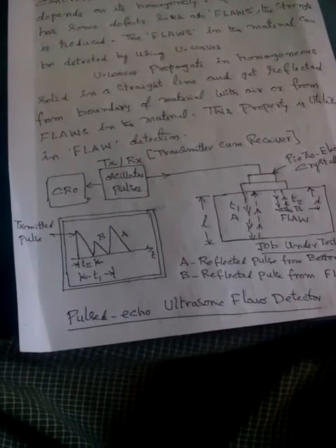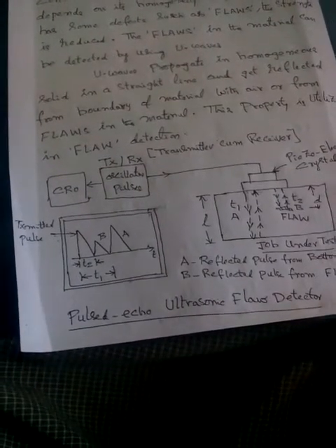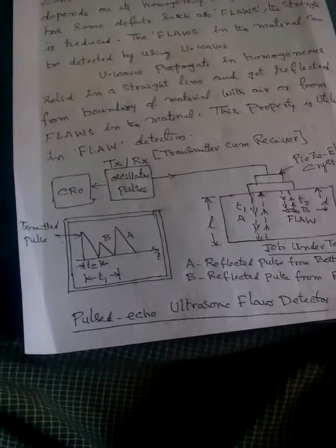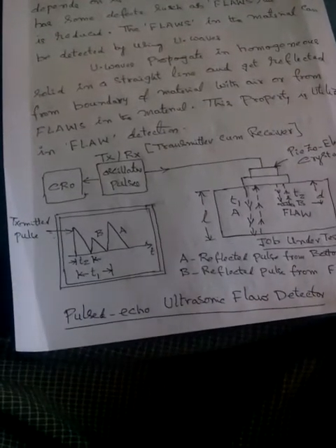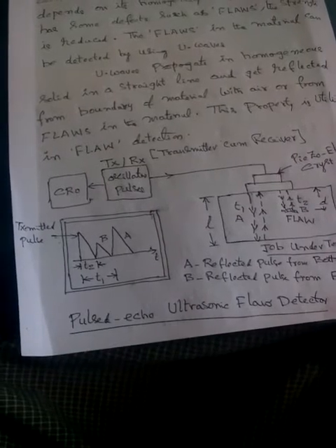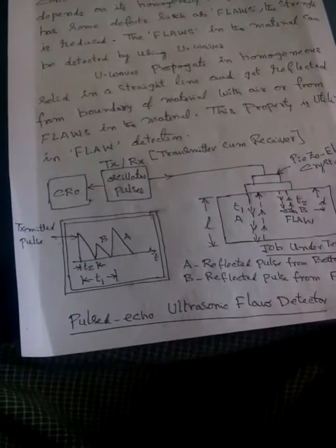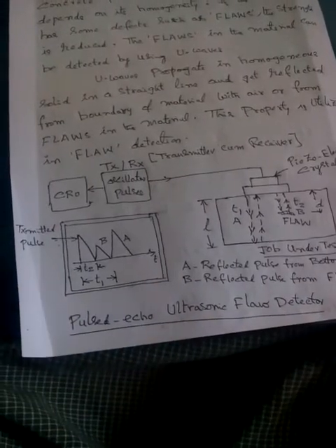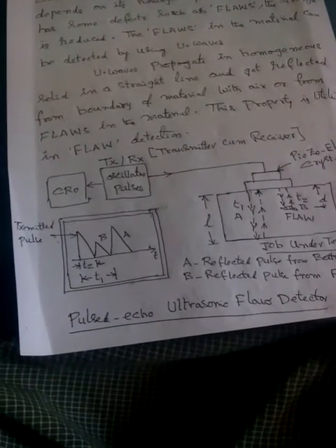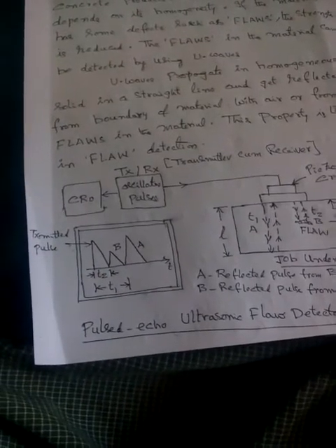If there is no defect, we get pulse A. It goes full length, full depth. Takes time T1. If there is a defect or flaw, it goes up to depth D, case B. So the echo returns back within short time of T2. So that you can see on the CRO. That's how it works.